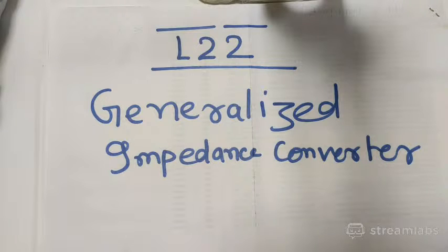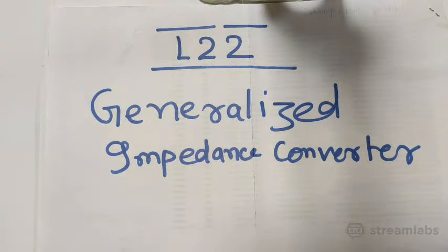For a voltage source there is a resistance or impedance in series with the voltage source that comes naturally. This impedance is small, but it comes in series with the load. If the load is also small, then it is a very big problem. Therefore impedance matching is required. Similarly, there is a problem in the current source also, so for that also impedance matching is required.